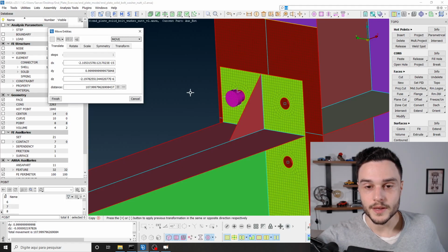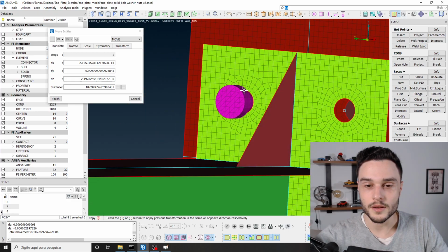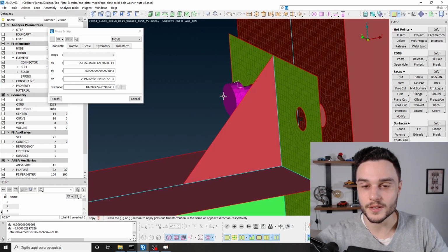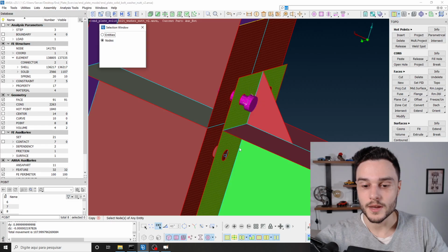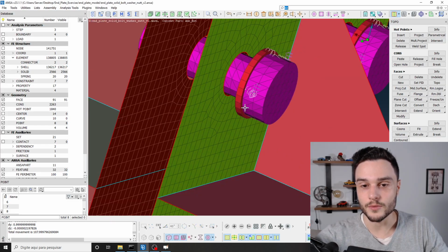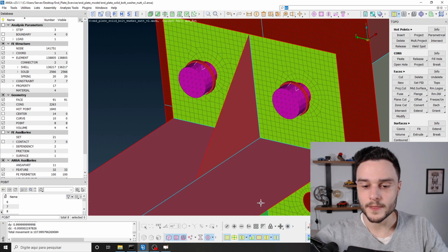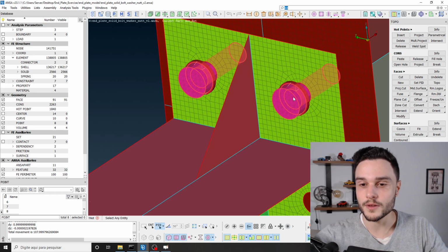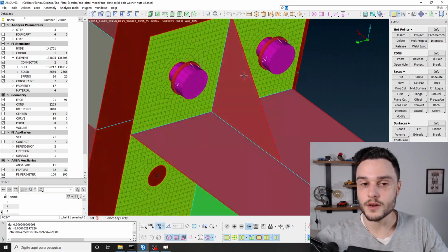Click on OK. And now we have the bolt there. Why don't I have the nut visible? Let me check one thing here. Click on finish. And now click on show all. Oh, okay. Now we have the nut here. Okay, so you see that in this copy, let me use the not function, property ID. This new bolt is part of the same property as the other bolt. And this is true for the washer and nut. Okay, so that's the meaning of that option, no offset.